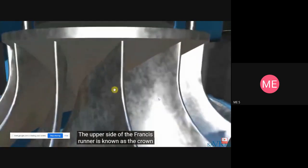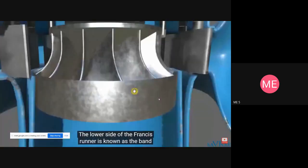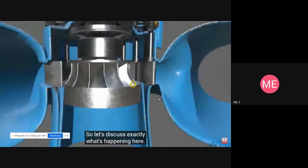The upper side of the Francis runner is known as the crown, and that's where the runner vanes connect to the top of the runner. The lower side of the Francis runner is known as the band, and that's where the vanes connect on the lower side. So let's discuss exactly what's happening here.